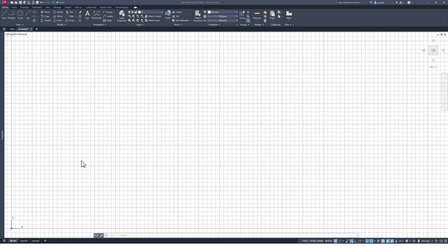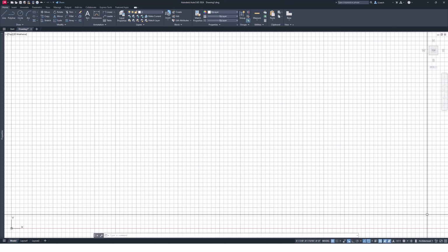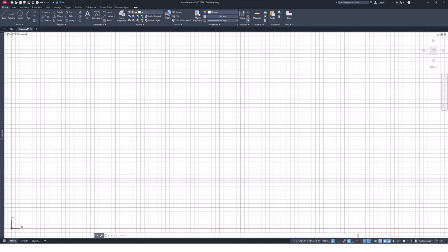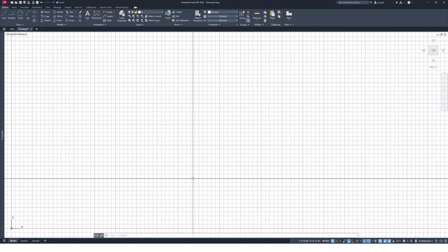So what I'm going to do is I'm in AutoCAD, right? But I am going to change my units. Now this is probably decimal units, but I am going to change it because I have an architecture class. I'm going to change my units to architectural, and I'm just going to use inches for this, not feet. So starting at exercise number 22. Now I'm going to show you the way that I usually draw